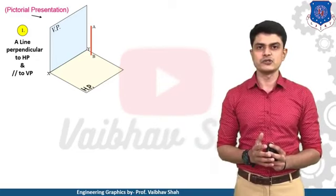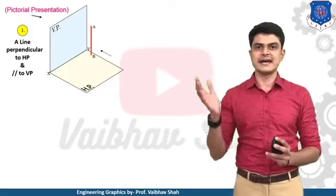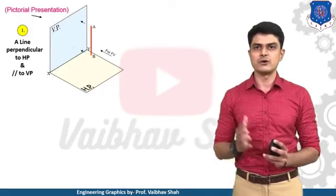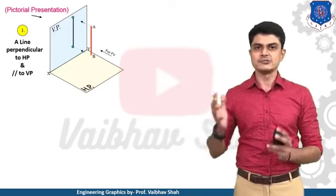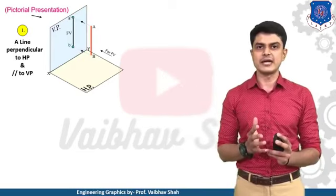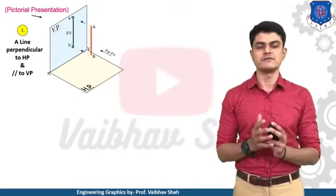Let us take the two views of this line. First, from this direction, is known as the front view. The front view will have one line on the vertical plane like this. It is the line having the same length as our actual line AB. This is nothing but the front view on the vertical plane, and it is denoted by A dash and B dash because we are denoting the front view of the line.